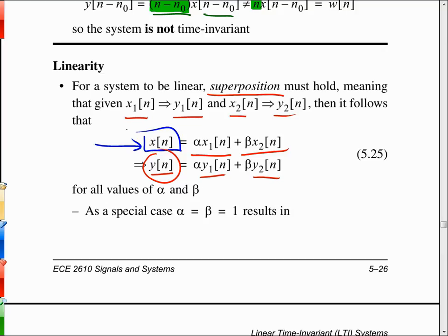So there's an increased likelihood that I'll start driving the amplifier stage into distortion, and it will sound distorted. That maybe doesn't sound very impressive, but that's a tendency I think people would have. The music is already loud, so let's crank the gain on the microphone up louder to make sure that voice can be heard, and then you end up with a lot of distortion because the system can no longer handle that superposition. So that's an example of a nonlinear system.